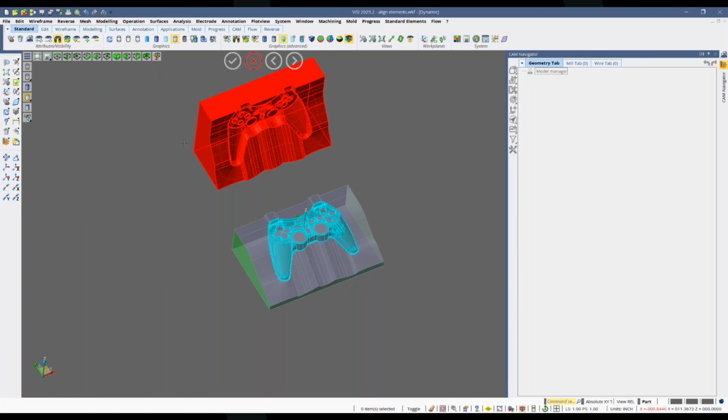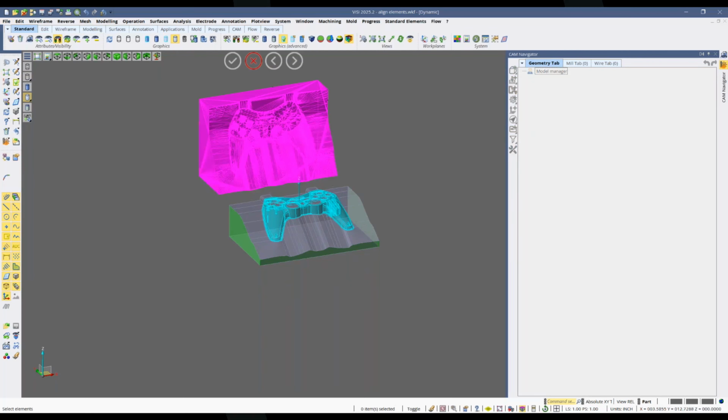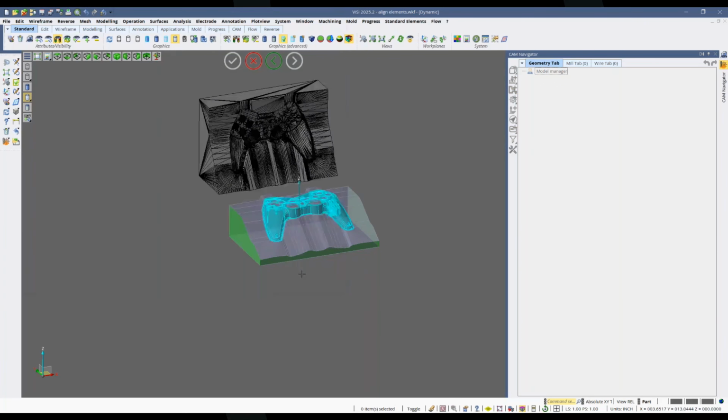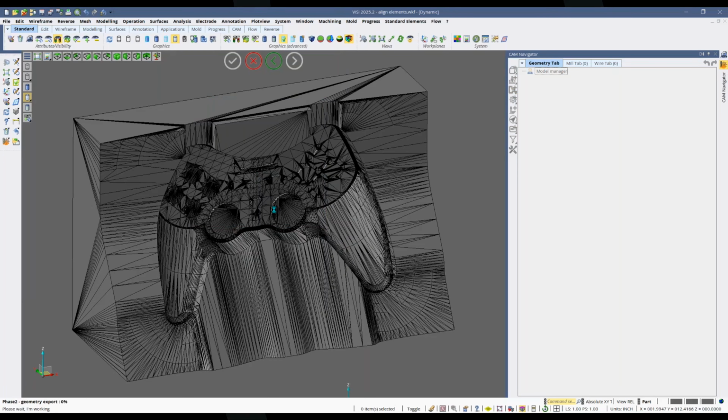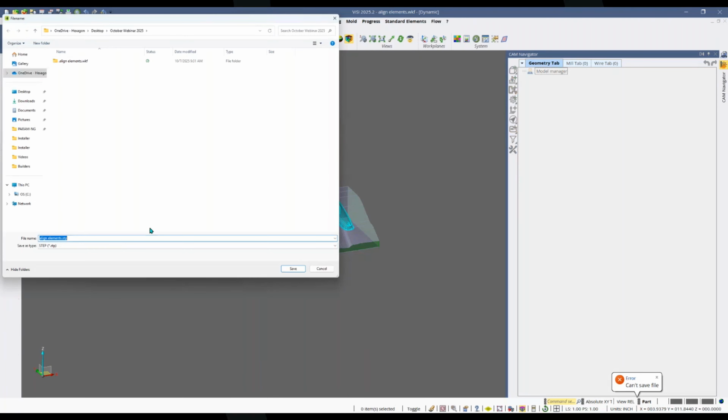Solid mesh. So when you want to export this out, you can just turn that off, which we went over earlier. STL is what you would want to select if you want to export out a mesh file, whereas a step file is made for surfaces and solids. So if I try to save this out as a step file, my file should be empty or not even possible. But if you save it as an STL, you should be fine for exporting out the data.